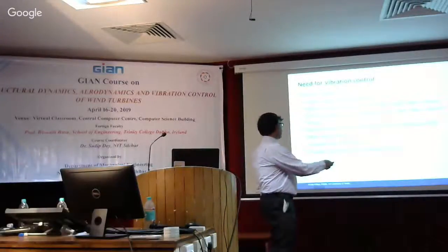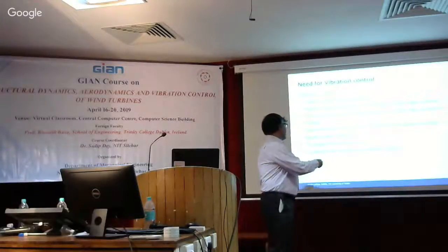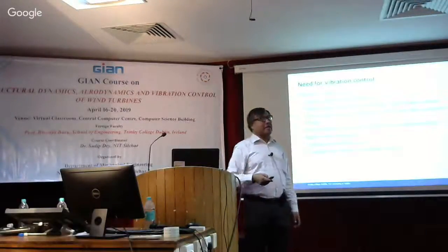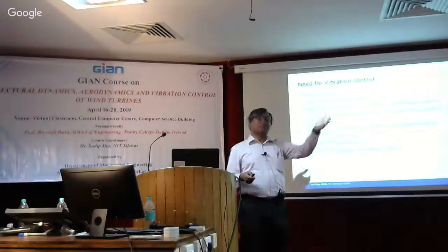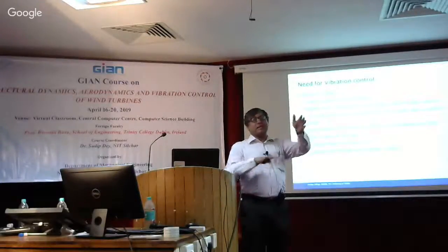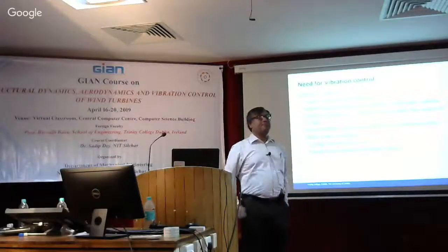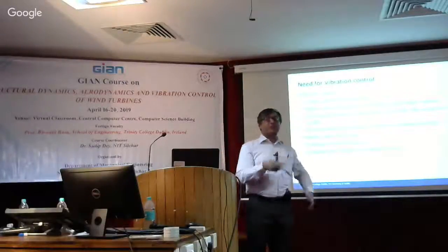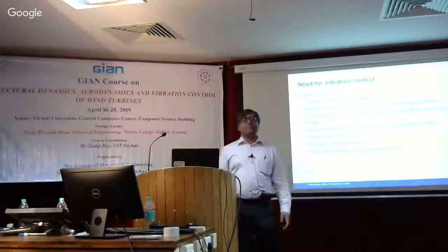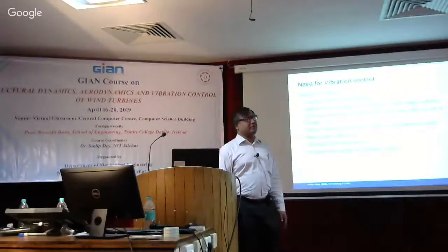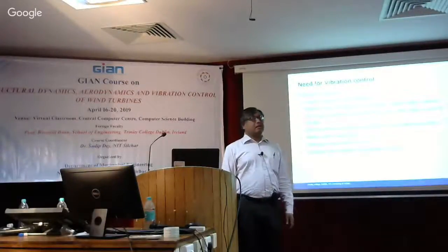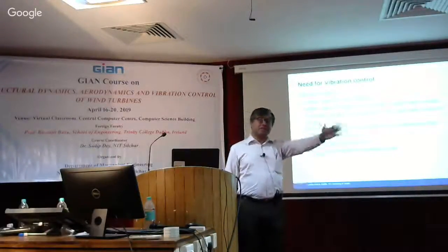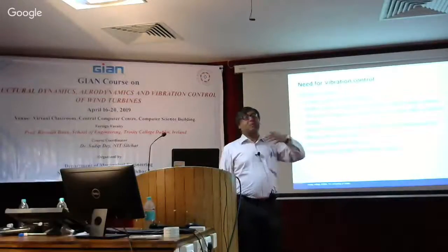And actually, for offshore wind turbines, it threatens the stability of the entire system. Because if you have a blade vibration problem, you're trying to control it with pitch control, and that controller has some delay with your platform motion, the whole system can get destabilized. And this has been very recently observed, 3 or 4 years back, in a large offshore wind turbine, when there was some oscillating motion of the platform, and they tried to stabilize it by using the pitch control, but it actually made the thing worse.